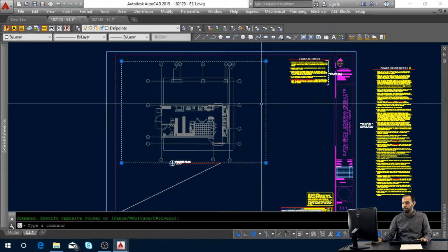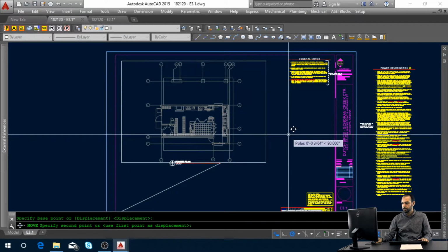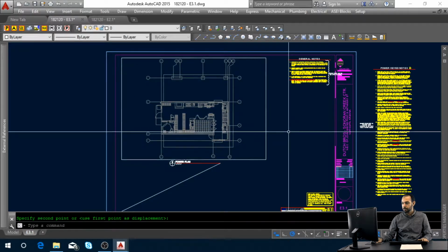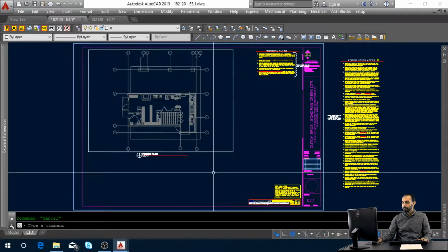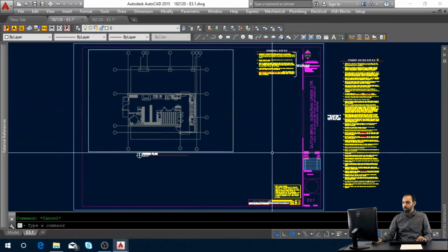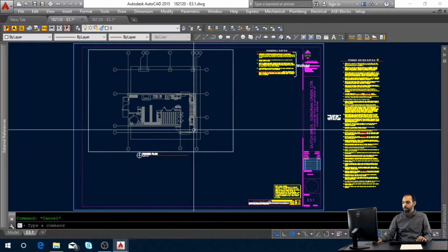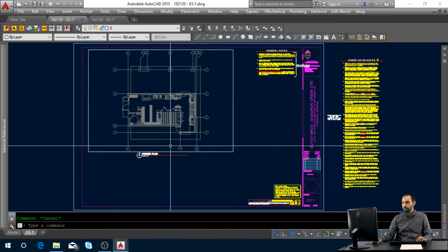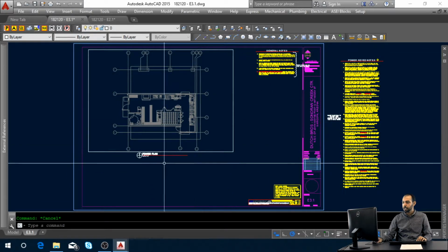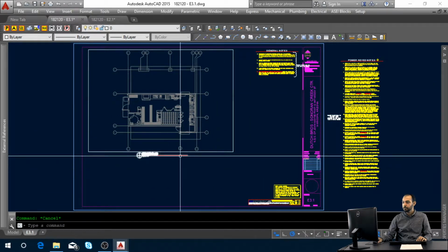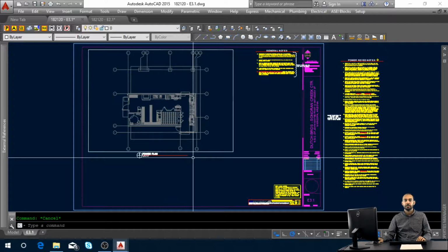What I can do is move my viewport up a little bit, so that way everything lines up. In certain cases, you'll have a lot of information, or the viewport background will be too big. This can adjust in those cases, but typically you want everything to line up as best as possible. And this is everything that you'll need to finish your sheet setup for the power plan.